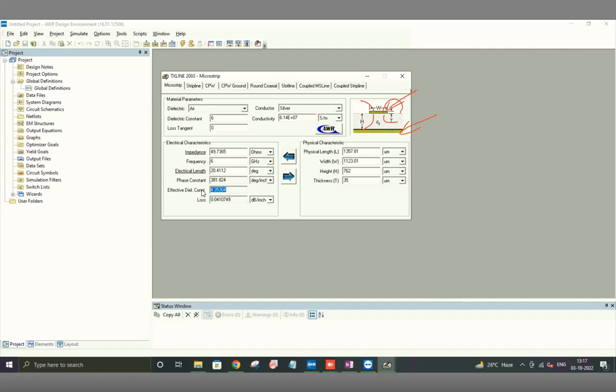So you can make it. This is the lower part, that's the ground plane. And the holes are again for the same. There are no holes. No, those holes are again for the connector, not for ground stitching, there's no ground stitching going on here. Yes, but here there are no grounds which have to be connected. There's only one ground. So this is convenient because there's only one trace going, but it's not so convenient if you want to connect something between the center pin and the ground plane, because now the ground plane is buried.